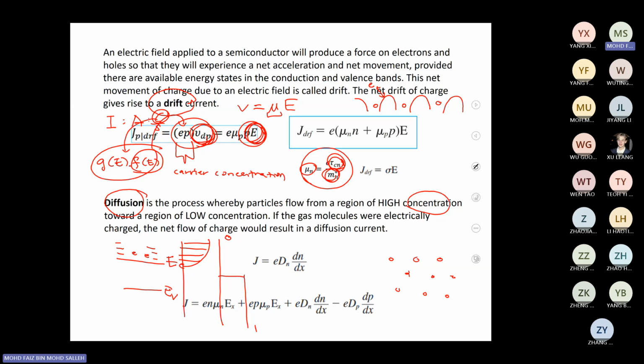So this ion will also interact with that electron. That's why we call it ionized impurity scattering. The electron scatters with the ionized atom, in this case the phosphorus atom, to make it N-type. And the other one, the most governing scattering process, is phonon scattering, which is the lattice itself, the silicon.